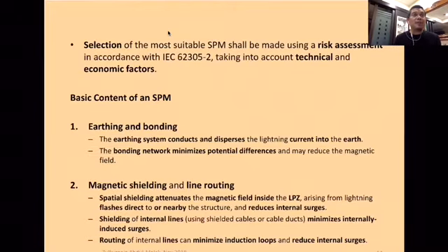Apart from shielding, you see, shielding will limit the radiation from outside. But you can also have current flowing in the down conductor, and therefore the magnetic field still can go inside the house because there is a conducting current through the down conductor.